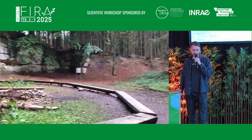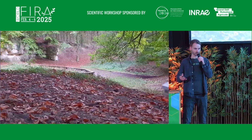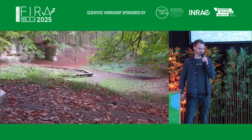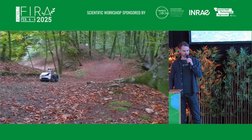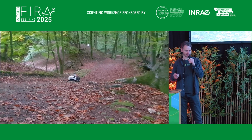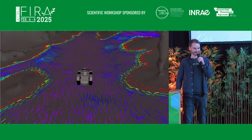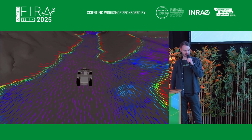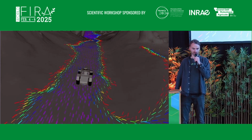We applied that in the forest, showing that we can also apply this to any other environment, for example, on the field. Here the robot is equipped with a LiDAR, so it's localizing with the LiDAR, because in the forest you have no proper GPS and RTK localization, right? So it's localizing in the map with the LiDAR and then driving alongside the vector field.